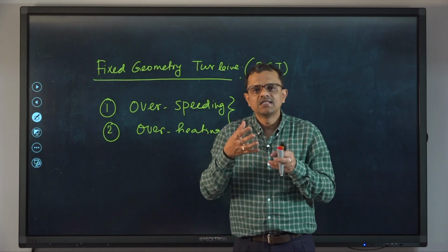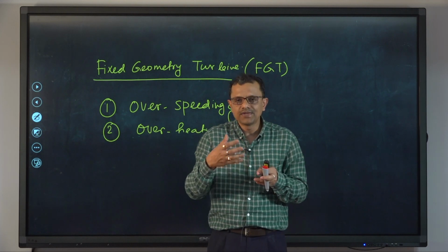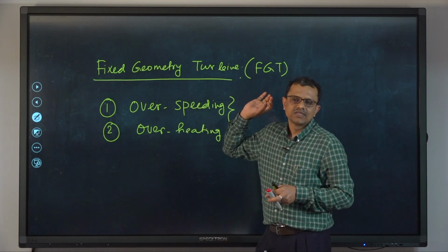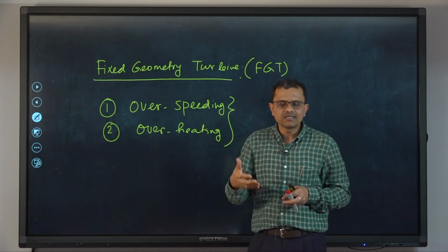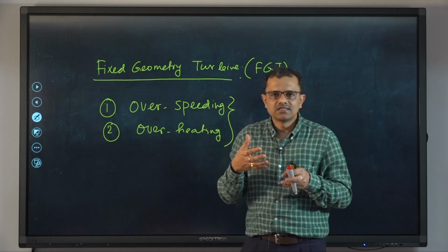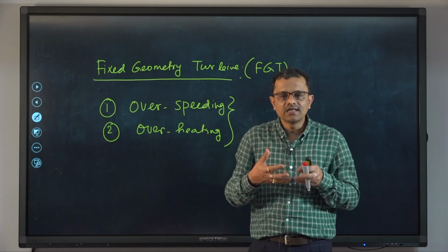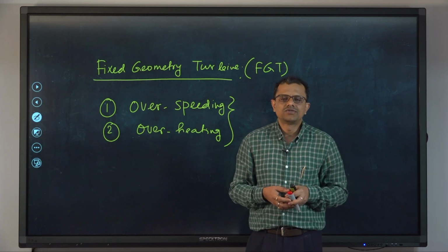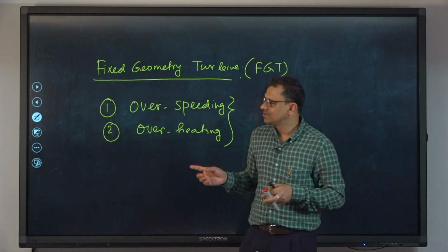If the inlet air pressure is higher because of higher speed of the turbine or compressor, in the subsequent stages of operation the temperature of the charge or incoming air will be more, and that high temperature may become vulnerable to several parts of the engine. This is known as overheating.